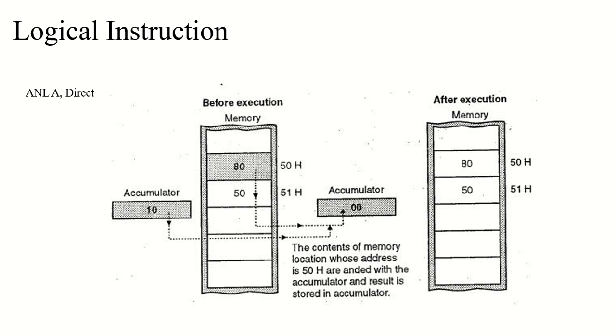So now that that is out of the way, let's start with the logical instructions. In logical instructions, it will be pretty much similar to the arithmetic instructions and the data transfer instructions, except we will be executing some different instructions from the previous ones. So first we are going to discuss the ANL instruction. On the left we will have the destination byte, on the right we will have the source byte, just like the previous two instruction sets.